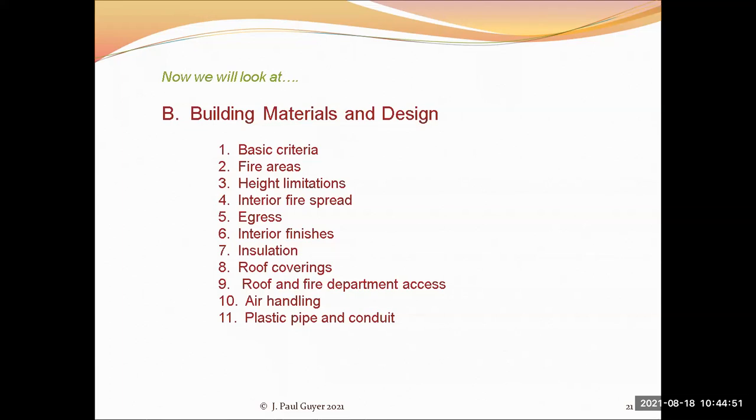The typical simplistic example of what the firefighters are doing is they drive up to the side of the building and they deploy a pumper truck that has a pump in it. So they'll take a hose, run it from the fire hydrant in the street to their truck, and then it goes through the pump where the pressure is increased, because the street pressure of the typical municipal water system will only get the water up to a limited number of stories vertically, 10 stories or something like that. So if you've got a 20 or 30 story building, you've got to increase the pressure of the water in order to get it to the top of the building.